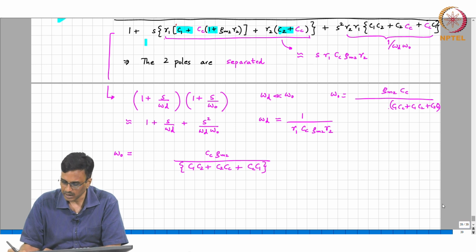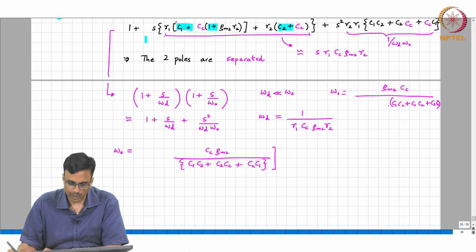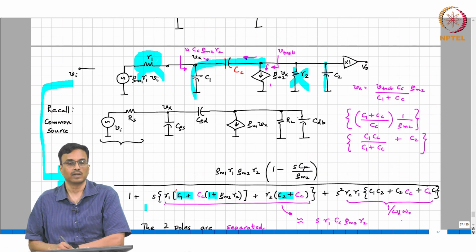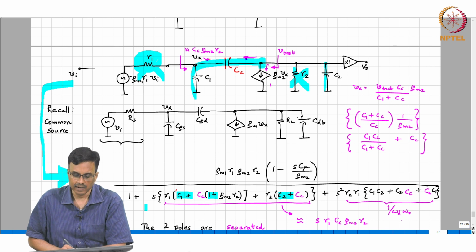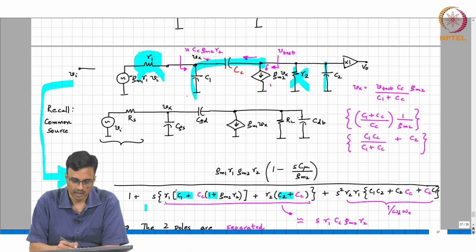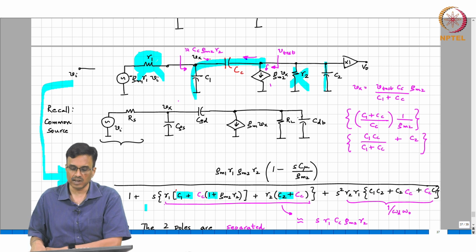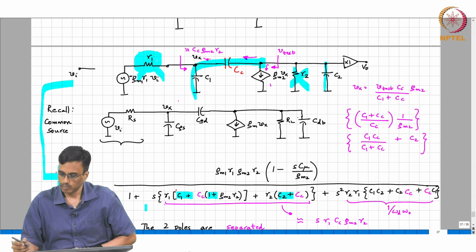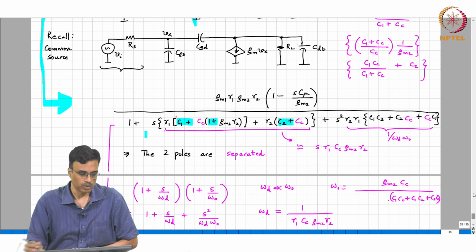But the intuition behind why you get this result is that at high frequency, the currents flowing through R1 and R2 are all negligible, and the system you have is basically just C1, Cc, Gm2 and C2, and the time constant corresponding to the pole frequency of that system is this expression over here. Okay. All right. So, I will stop here, we will continue in the next class.